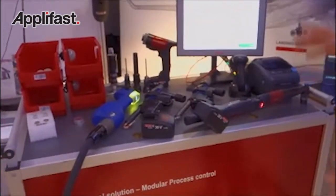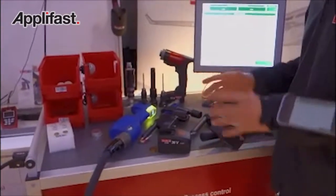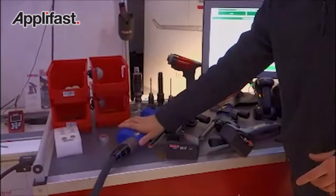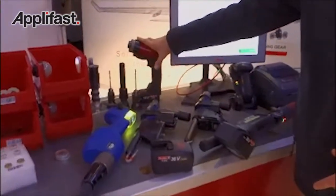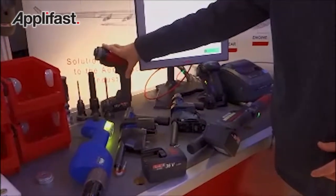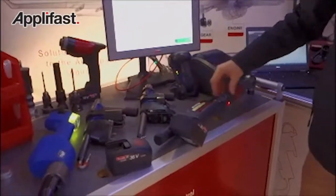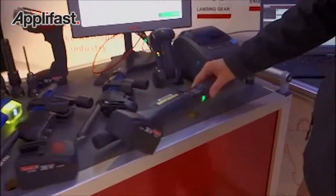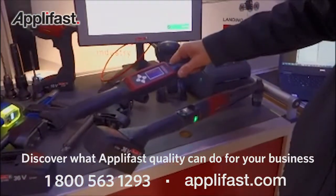Then we move to the tools. What we will show is how to sequence and how to pilot and control your process, including feature drilling with the EVO, with different heads, including temporary fasteners or drill jig fastening and clamping, as well as manual drilling with the prototype of Easy. We will see as well the different potential that we have for the tightening and how finally we can control the different measurement equipment that we've got.